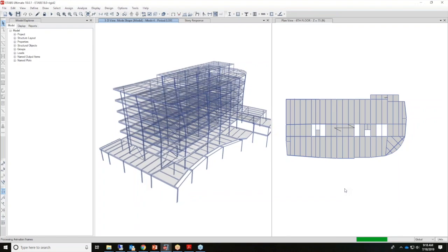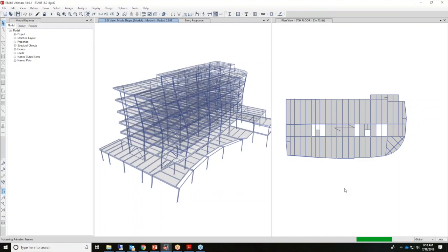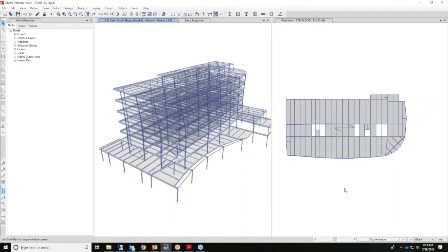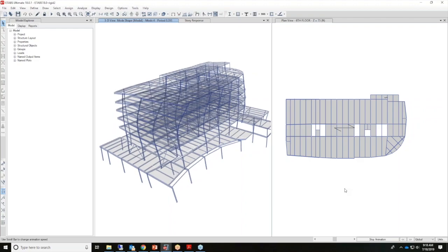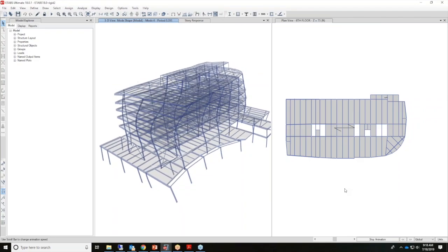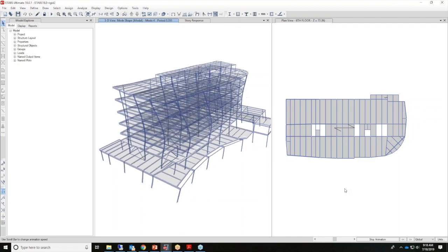I'll show you how to view output using the tables, as well as joint displacements, diaphragm accelerations, and the very important participating mass ratios. So hopefully that's coming through. You can see the rotational mode here, mode 4 with a specific period.